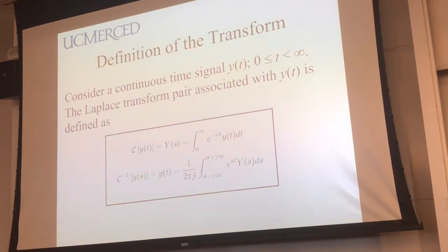If you forget zero minus, you will be in trouble. Your results could be wrong, okay? Because otherwise you cannot handle a situation like a capacitor previously charged. Then you switch, and that pre-charged state is kind of an initial condition.